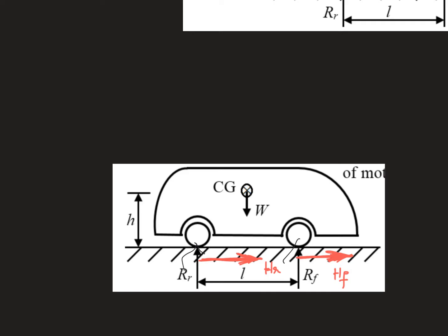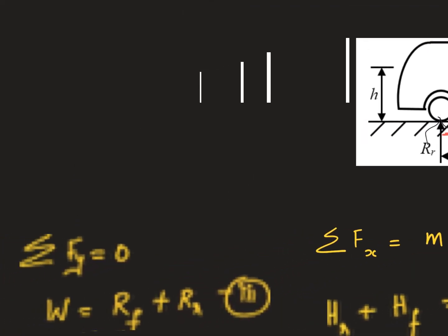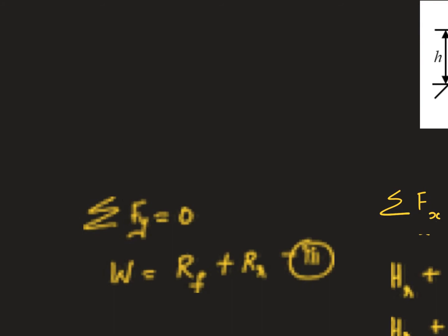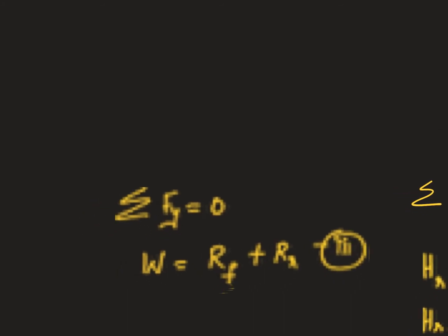Now it's fairly easy because we have identified the external forces that are acting on the system, and we have removed all the supports. So let's sum up the forces in the y direction. I am assuming the positive direction along the y-axis to be the positive sense for the forces. Then we get weight W equal to the sum of those two vertical reaction forces.